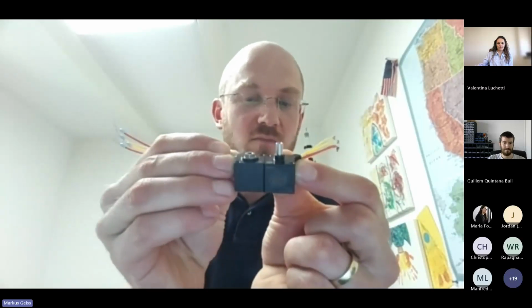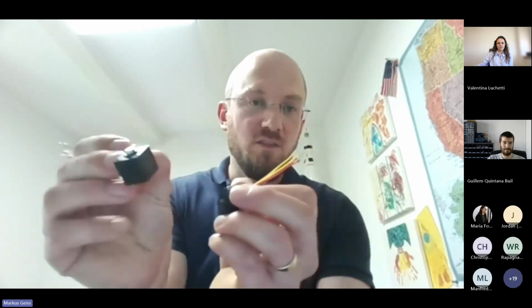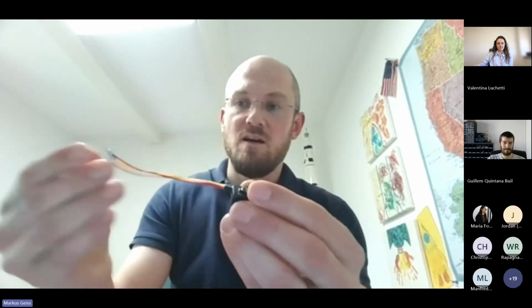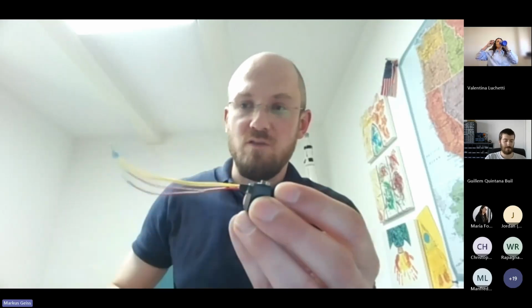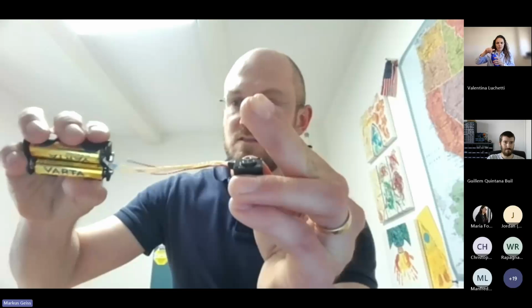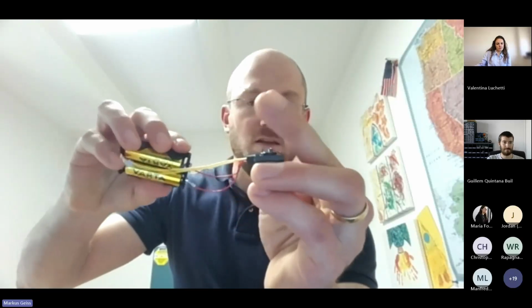If you don't have a shear load application, but let's say you have an axial preload case that you want to constrain, you better use the release nut. It's the same form factor, same internal shape memory mechanism, but instead of the pin going in, this has the nut come out. Again, redundant trigger line, so I just power up one of them, and what you'll see is, oh, get that right, the release nut coming out.